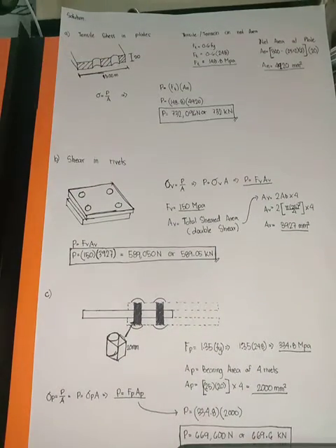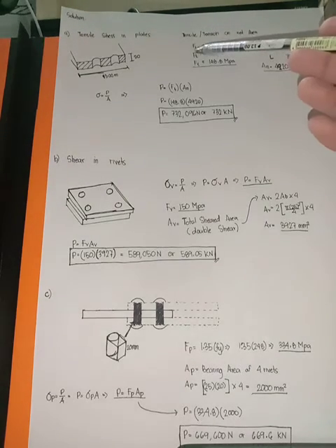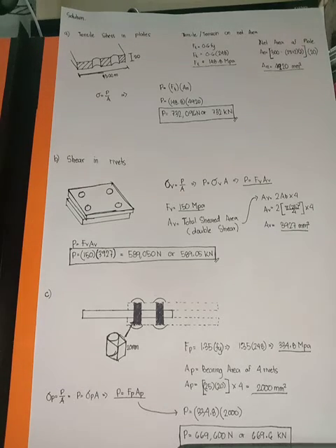So for our first unknown, which is the tensile stress in the plate, before we proceed, let us identify the tension on the net area, which is equal to Ft. So our tension stress is 0.6 Fy. Then our Fy is given, which is equal to 248. So 60% of 248 is equal to 148.8 megapascal.